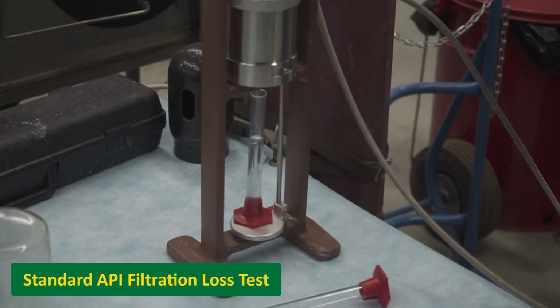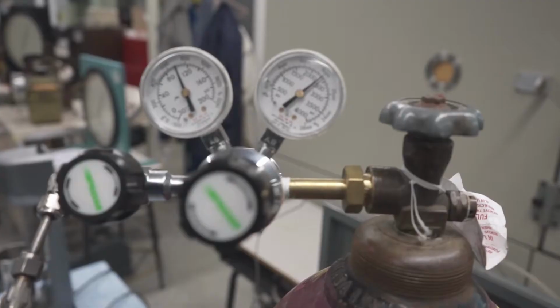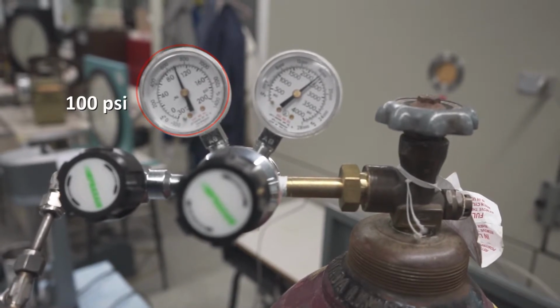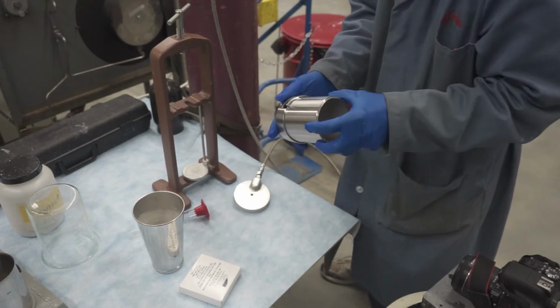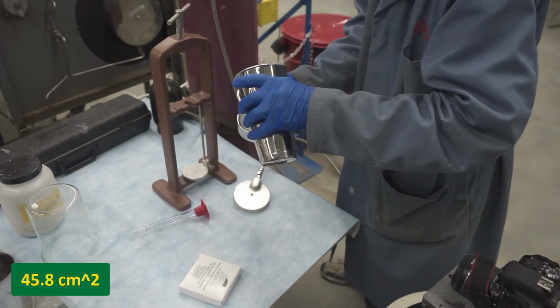In order to measure the fluid loss, we use the standard API filtration loss test apparatus. The test is conducted under 100 psi nitrogen pressure, which is applied to the drilling fluid placed into a standard cylindrical filter press cell, which has a circular cross-sectional area of 45.8 centimeters squared.